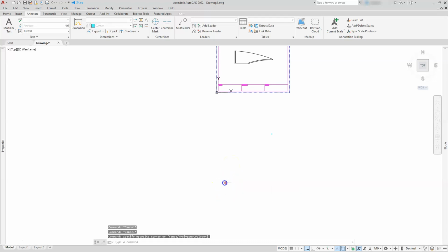Let's go ahead and move this first plus, and I'm just going to move it going straight up. Once again, I'm using my tracking onto this. And remember the O-snap tracking, if you're looking for it, polar tracking is the one that I'm using. So I can use the polar tracking, and then that'll make sure that it keeps it going straight up and down. And somewhere around in this range.